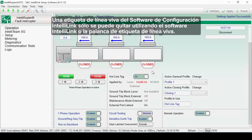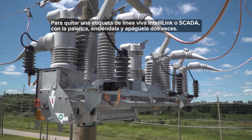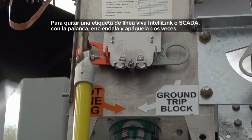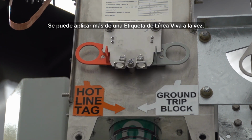An IntelliLink Setup Software Hotline Tag can only be removed using IntelliLink software or the Hotline Tag lever. The SCADA Hotline Tag can only be removed by SCADA or the manual lever, and the lever Hotline Tag can only be removed by the lever. To remove an IntelliLink or SCADA Hotline Tag with the lever, cycle it on and off twice. More than one hotline tag can be applied at a time.